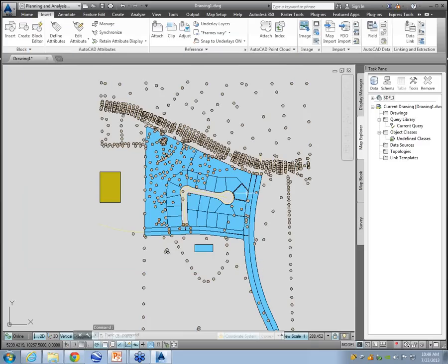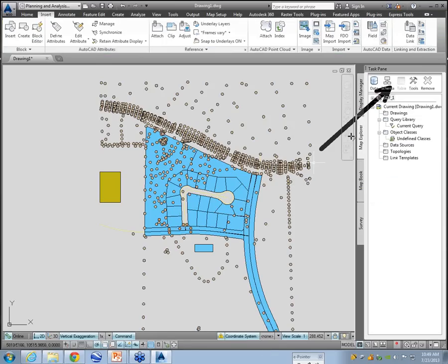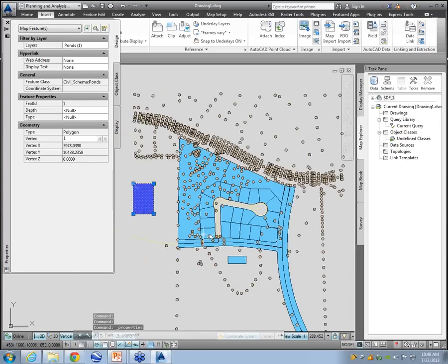So as you see here, what I just did through all these quick steps is I had objects in my drawing, and I said, look, these objects in my drawing represent something that I don't have as a layer over here. So I added them as a layer. I then went into the schema editor and I started editing the schema. In other words, adding attributes and tweaking my attributes. Now the last thing I have to do is grab the objects and actually modify those objects in my Control 1, in my properties window, over here.